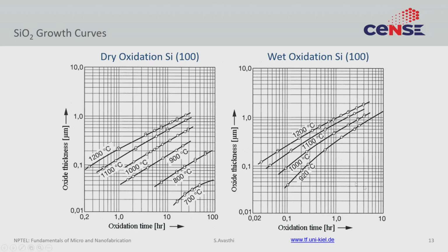In the previous few lectures, we went into quite some detail into the exact mechanism of how silicon dioxide is grown on silicon wafers by just providing an oxidant, either dry oxygen or wet oxidation. In both the cases, because of the detailed differences in diffusion, solid solubility, etc., the growth rate is very different. Wet oxidation is much faster, dry oxidation is much slower. In general, the quality of the dry oxidation is much better, the quality of wet oxidation is a little worse.